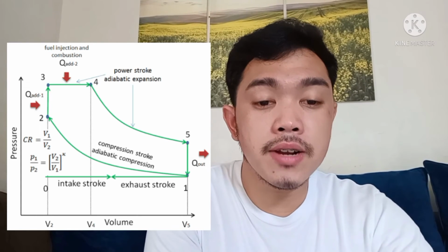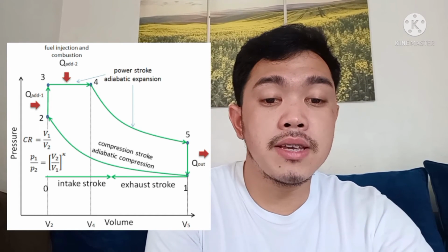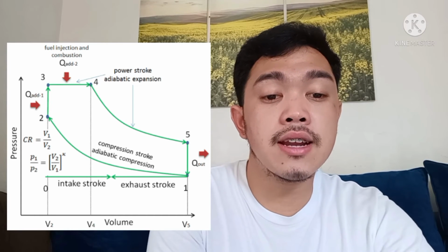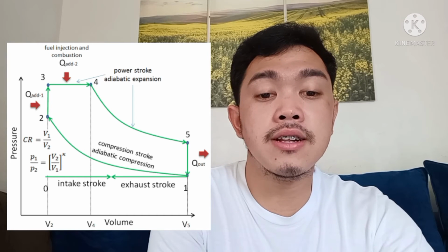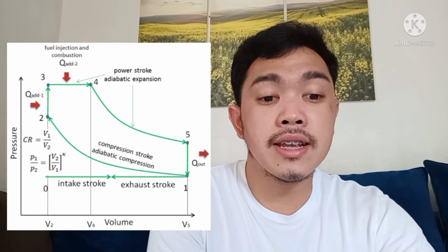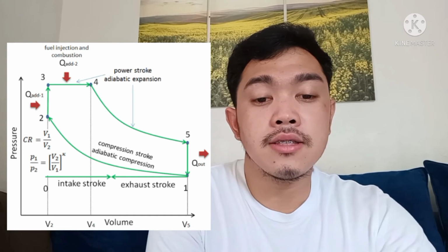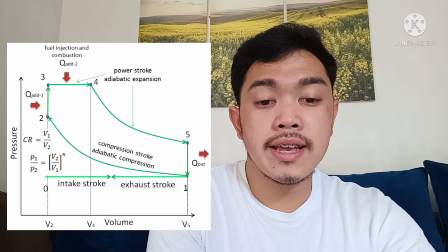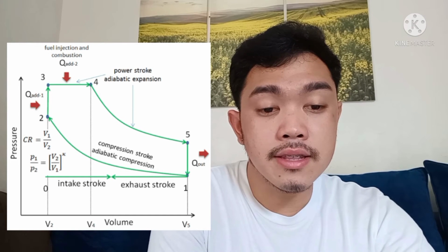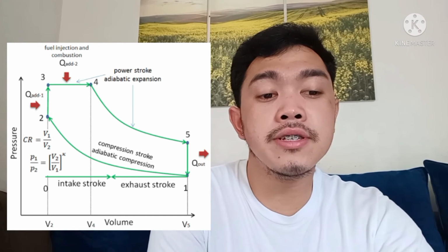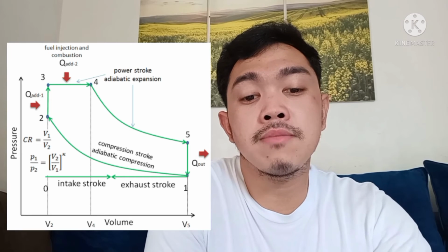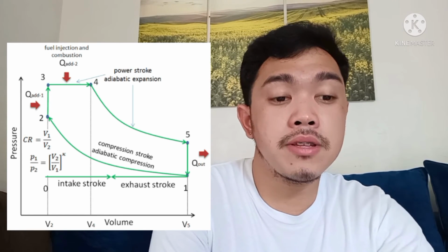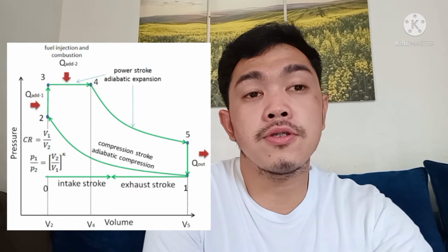Next is the isochoric compression or ignition phase. In this phase, between state 2 and state 3, there is a constant volume heat transfer to the air from an external source while the piston is at rest at top dead center. This process is similar to the isochoric process in the Otto cycle. It is intended to represent the ignition of the fuel-air mixture injected into the chamber and subsequent rapid burning. The pressure rises and the ratio P3 over P2 is known as the explosion ratio.